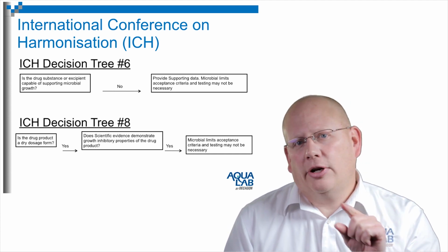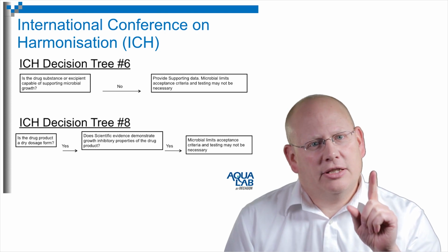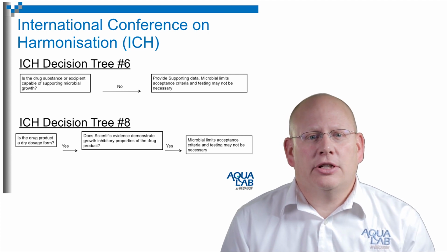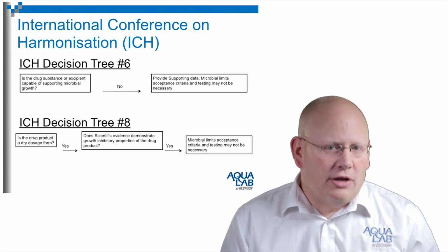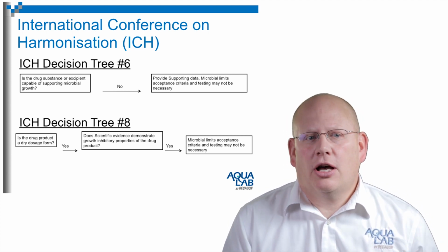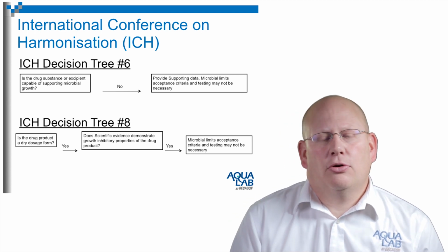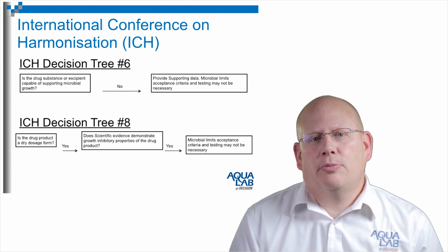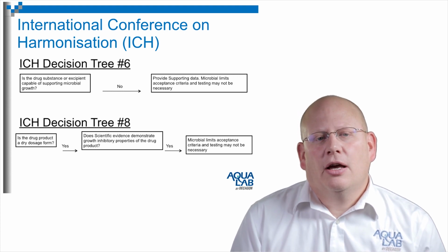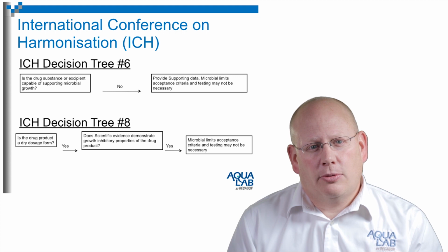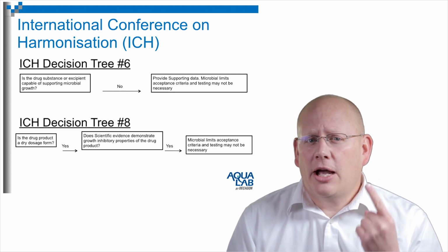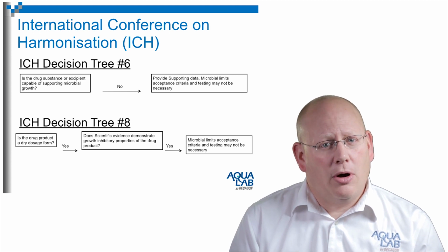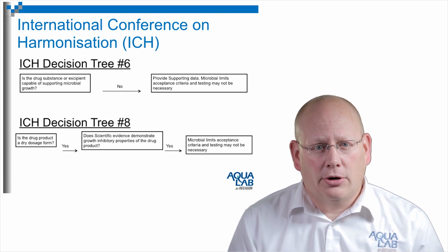However, there is no clear indication in these guidelines of what it means to be dry, or how you would track whether or not a product is inherently dry. The intuitive response is, well, they mean moisture content, and so we run Karl Fischer on those types of products. But in reality, moisture content has no relationship whatsoever with microbial growth. Water activity is what actually determines whether microorganisms grow. A microorganism doesn't care how much water is present. It cares what the energy of that water is and whether it can access that water or not.